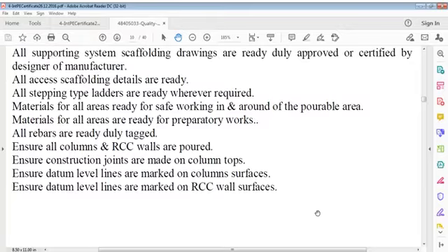Don't concrete that small portion, and we take it with us when we do suspended slab preparatory works. All columns are like that, except I think the stairs column, which is different. Non-stair columns are done that way. That's not about construction design, because now we are going to extend those columns, a small portion of column at top, to be monolithic cast with slab and beams.